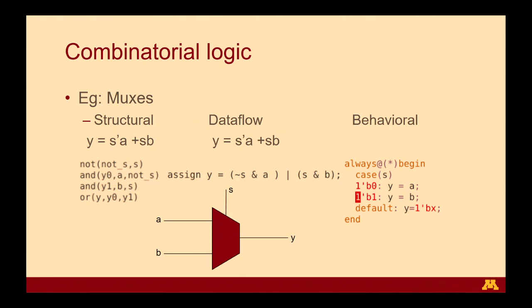So there are advantages and disadvantages to each. In the case of structural, you actually define the structure in the most optimal way you can imagine. Data flow is kind of in between in terms of optimization, and behavioral is usually non-optimized, and you leave the entire interpretation to the tools. So there can be advantages there as well as disadvantages.